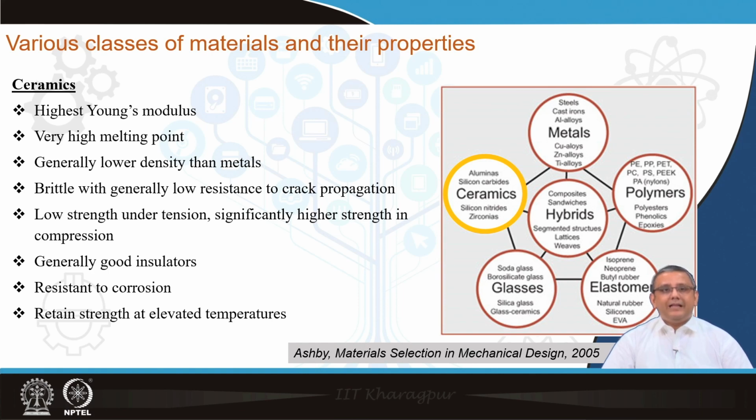So, all these things make ceramics an ideal material for many applications, but one big problem is that the one or two aspects which kill all the good properties of ceramics are basically its extremely high brittleness and its low fracture toughness. That means, when a hybrid is developed for a ceramic material or a ceramic containing material, the aim is to increase the fracture toughness, because ceramics already possess high strength and stiffness.